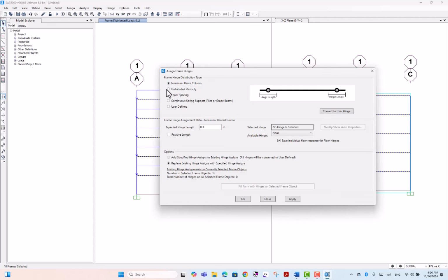So it also has distributed elastic, and the location is going to be 0 here, and you must select the defined beam that you want. And the location can be changed from 0.2 meters, which is about here, or you can actually use a relative, so about 0.1 or 10% of the length of this beam. So this one is also okay. So I'm going to apply.